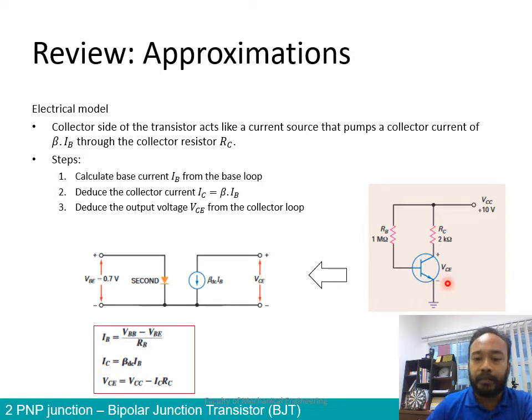In applications, for example in an inverter, in the power electronics of an electrical machine or a motor, it is this VCE, the voltage across collector and emitter, that is used to supply power to the load. The base part is the control part: the input we are controlling, switching on and switching off. VCE is the voltage that we are supplying to the load. The load is your application. It could be an electrical machine, a motor, or any other application as well.